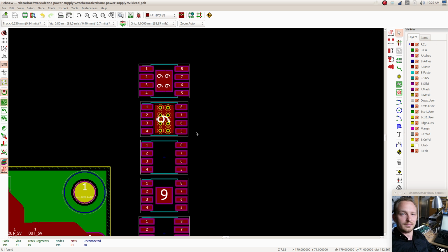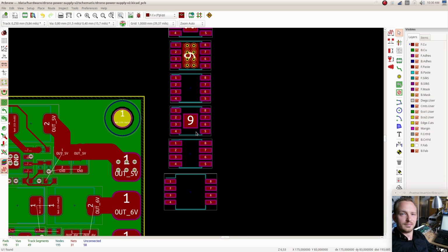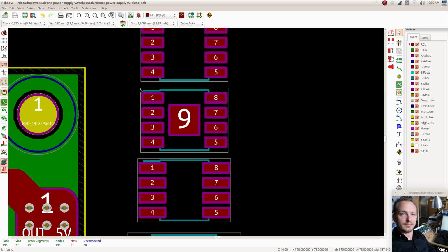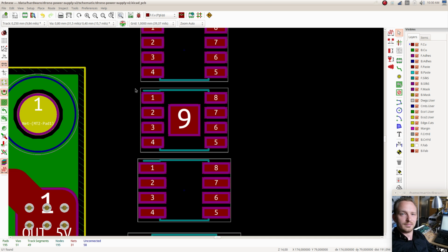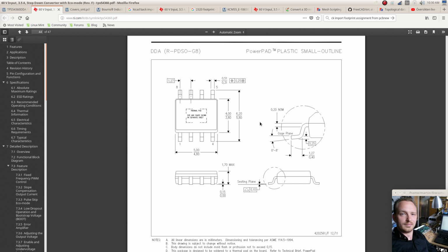But then we have 2 different variations. We have this one and we have this one. But then it doesn't say, let's say I want to have a different board density, so I want to change this border around the package, and there is no obvious way to do that in KiCad. There is no way to just enter a different number for this board outline and get the package automatically generated. Let's say I want to generate the package for this IC, which is 6.2 times 5.0.